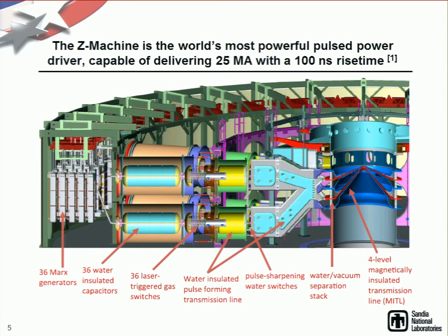Z actually has the capability to do pulse shapes, so you can drive specific isentropic compression experiments with that, or you can change the machine so you can either fire it in 100 nanosecond rise time mode or in 300 nanosecond rise time. So you can use those to set your timing, additional transmission lines, and basically just bringing the pulse in further to this point here.